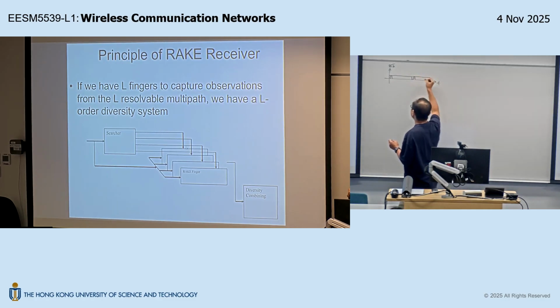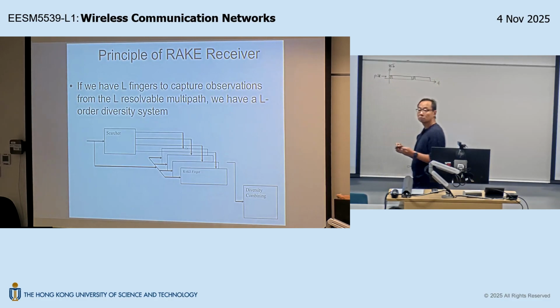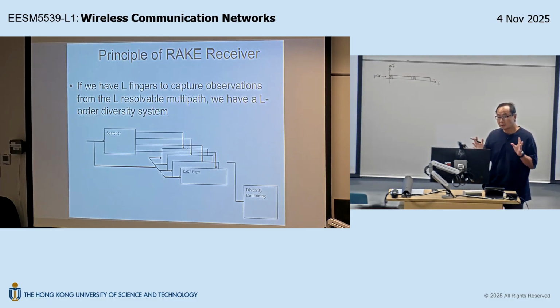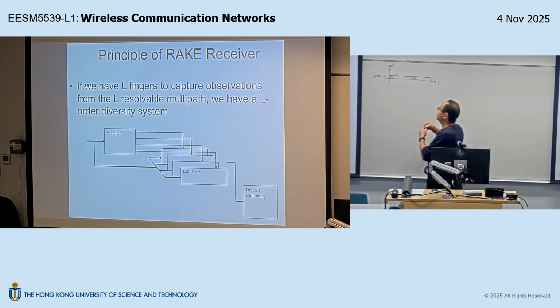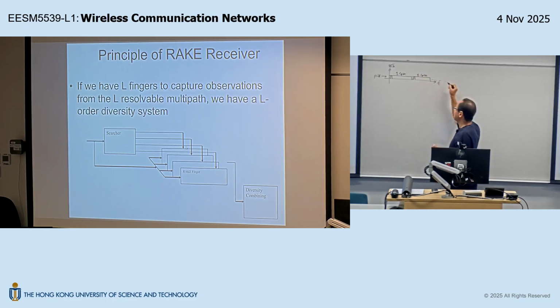The pilot channel is transmitted periodically. Now the pilot does not contain any useful data. The pilot is just like a known reference symbol. So let's assume the reference symbol is all 1, and then chopped into 64 pieces. So we have a pilot spreading sequence, and that would be pretty much the pattern of the pilot.